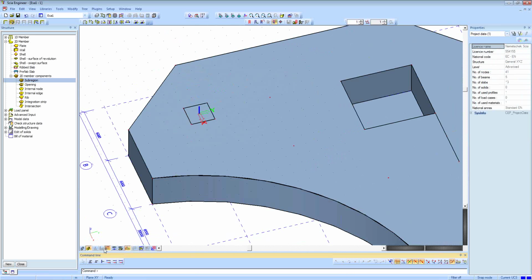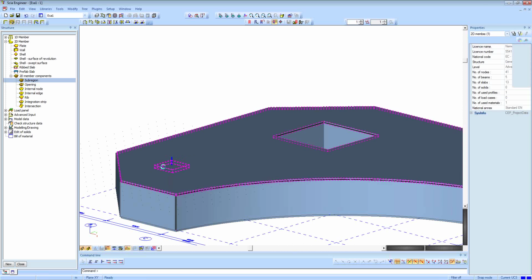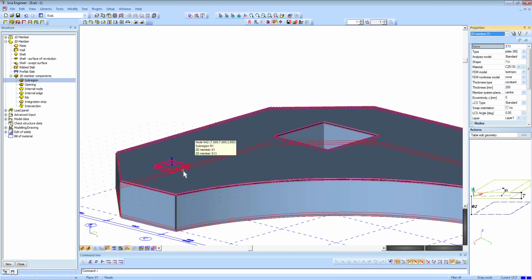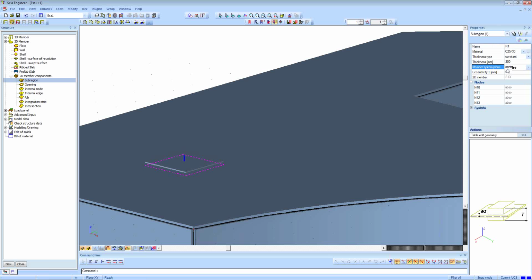And now I have a local region with different properties. As you can see, it's thicker. The extra thickness is divided over the two parts of the plate, the upper part and the lower part. Now, I can also do something else. I can say that I want it to be parallel. And if I choose top, I want it to be parallel with the plate at the top side, then the additional thickness has gone to the bottom side. Or differently, if I choose bottom to equalize, then you will see that the extra thickness comes at the top side. So let's say top again.